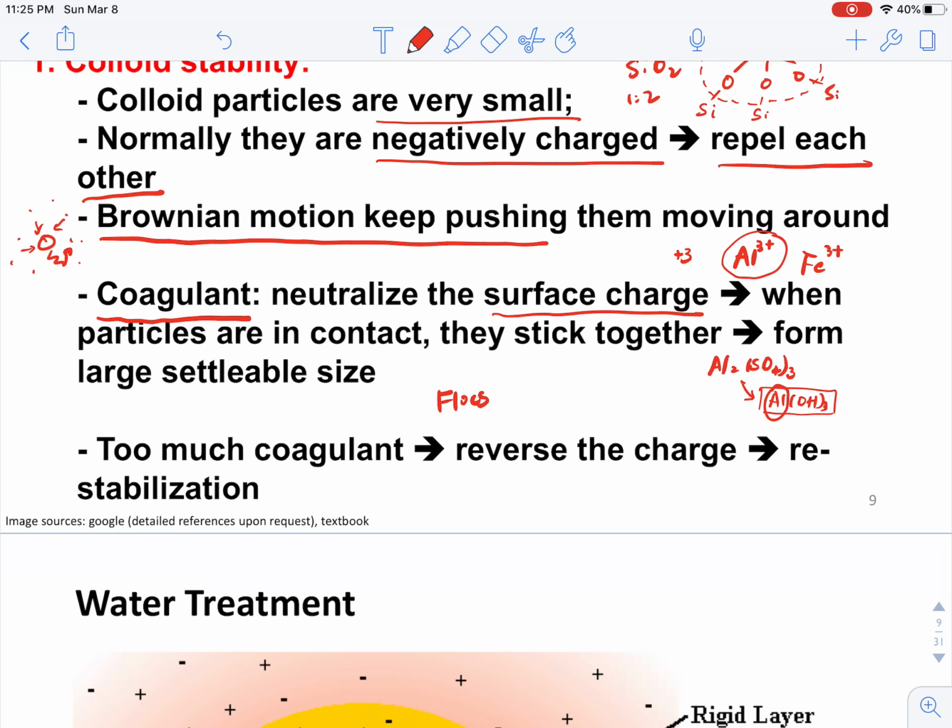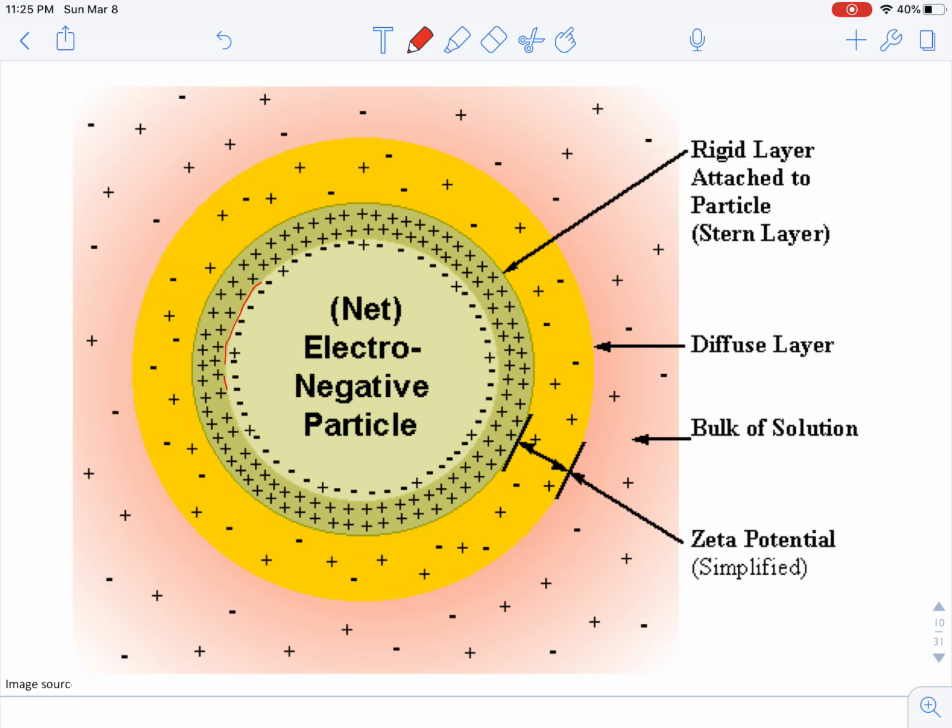So here, this is basically what I'm showing about the charges on the particle. Typically, this light green particle, or sphere here, represents a particle in the water, and they will carry a net negative charge, right? Because in the water there are a lot of dissolved ions, and they can first form a single layer surrounding this negatively charged particle. This is directly because of the attraction of different charges, right? And then further, this positive ionic layer is going to give this entire ensemble a positive charge.